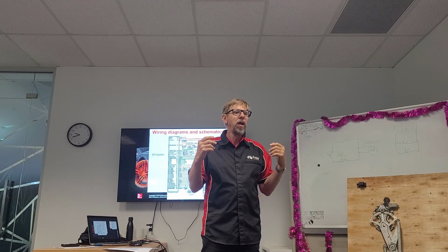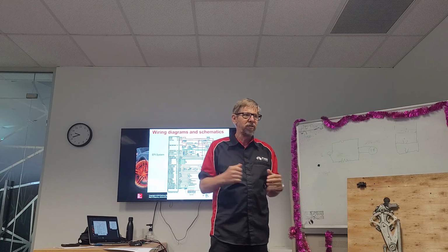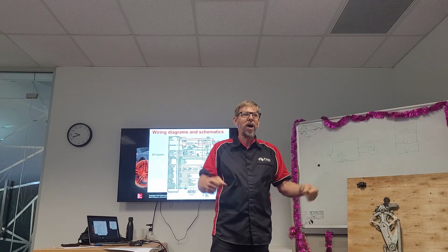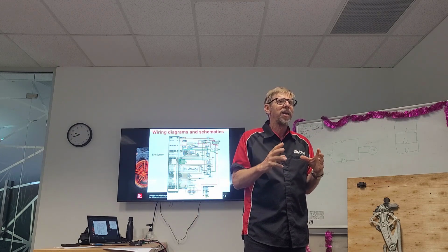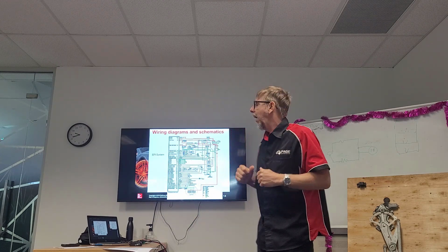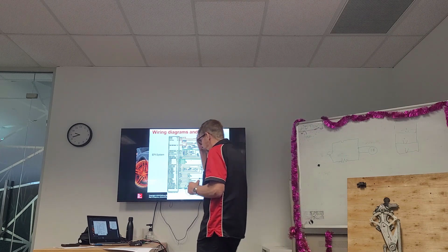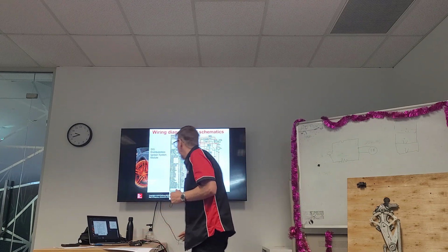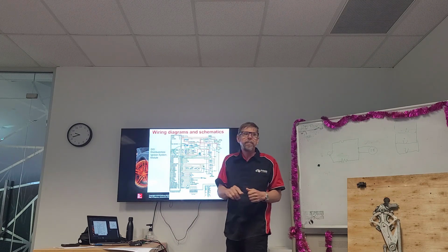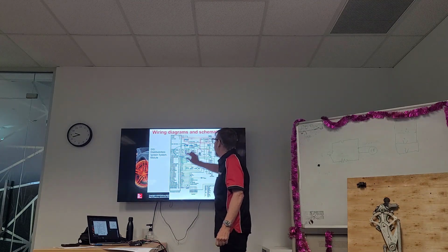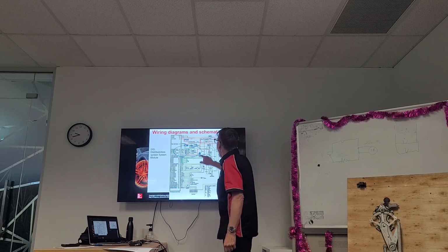So they only had half the coils to the number of cylinders, in other words, because of the way the pistons go up and down together, okay? So this is a waste spark ignition system, and distributorless ignition system also. So let's have a look at that. So here we are. Here's our module. See that? That's our ignition module. Okay? And this is the circuit.